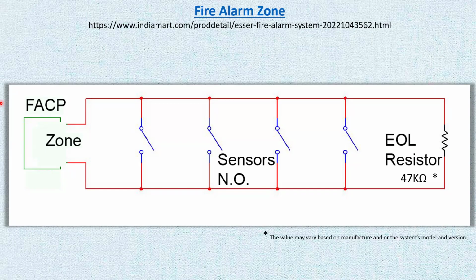There are certain things that need to be watched for. And yes, when filling up with, for example, the ABC powder, sometimes the valve wasn't closed properly. Well, things happen. Or sometimes when you pick up the extinguisher, you would accidentally discharge it.